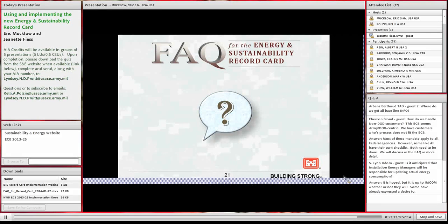Exterior lighting and things like that that's on the building or in the immediate part of the building, that would be included. But what I was talking about earlier was if you had a firing range or significant exterior lighting or something that was for an exterior space outside the building, then that would be something that you would not include. And usually on the 1391, those are treated as separate line items. So if you have security lighting and things on the building, then yes, those would still count.